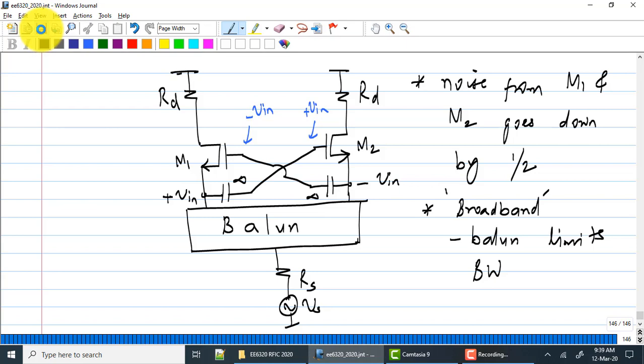Assume that you have an LNA with a noise figure, some noise factor F. You're going to build a pseudo differential version of that, with an ideal balun up front, ideal lossless balun. Please figure out whether the noise figure is the same or different in the two cases. You will need this because your LNA project does have an ideal balun, right? So yes, you will need to do this. In case there's any trouble, we'll try to do it in the next class.